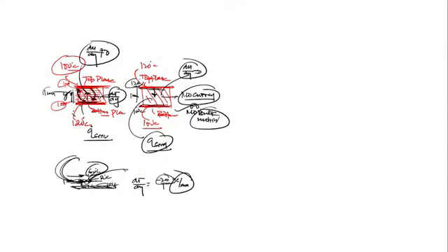That increases the temperature difference now to 100 minus 60, that is 40 upon 1 millimeter, degrees Celsius per millimeter. Now the temperature gradient will increase. So whenever the fluid is in motion, that increases the velocity gradient, and that increases the temperature gradient as well. Yes or no? And when the temperature gradient increases, the rate of heat transfer will increase. Yes or no? Tell me.